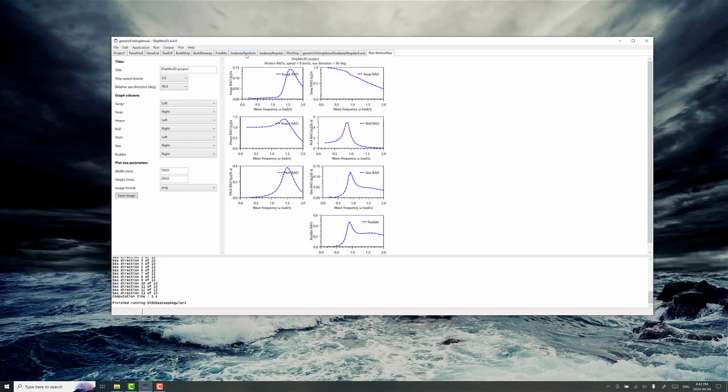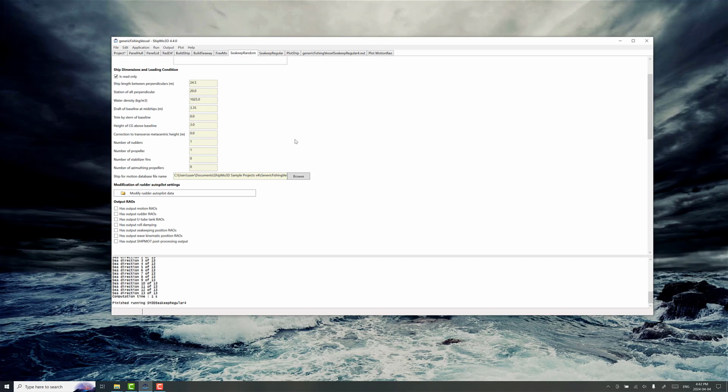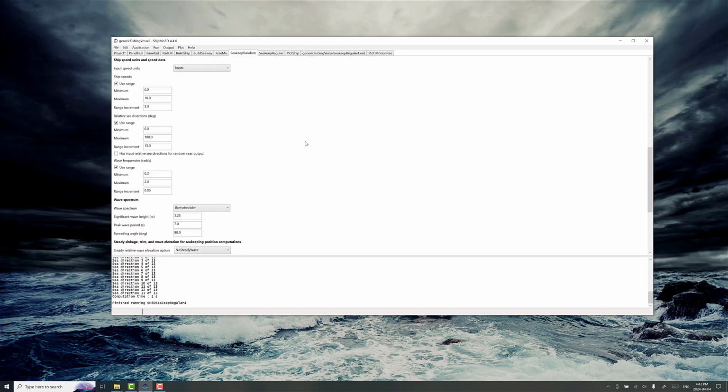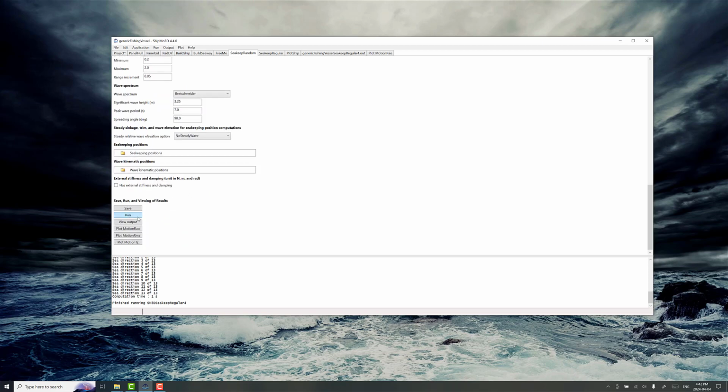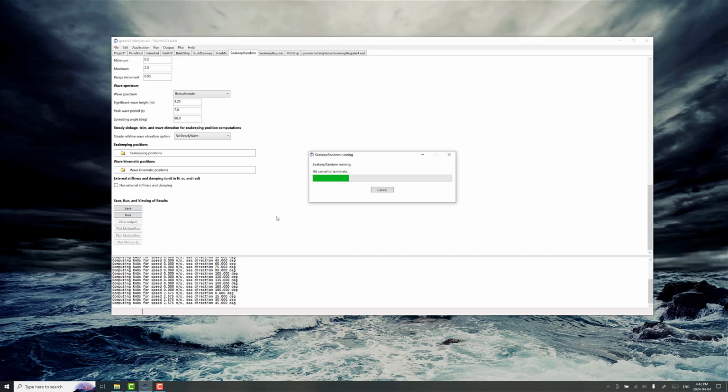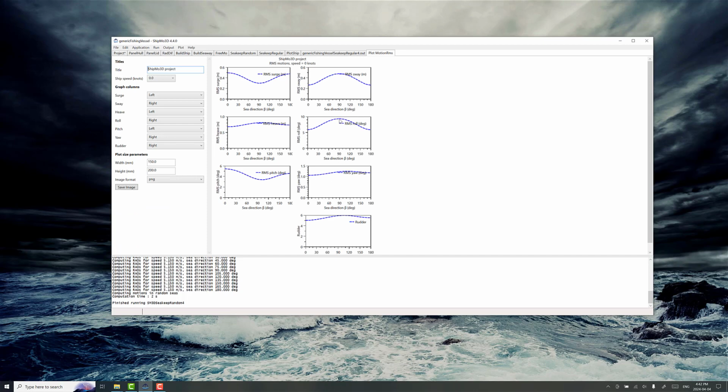Finally, the last thing is checking what happens in a more specific sea state. The RAO is all good, but it's not necessarily indicative of performance in what might be a much more interesting sea state. So with a spread wave pattern and an irregular sea state, we're just going to quickly run this case with the same ship. It's analogous to looking at what happens in regular waves, but it's nice to look at the RMS motion. At 0 speed, you can look at forward speed and all the different conditions that you want, but just at 0 speed and beam conditions, you can characterize that we've got this much roll motion.